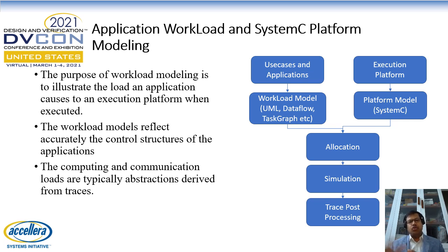And then we have also looked at an open source solution like a gem5 platform, which allows you to simulate different kinds of ISAs. It also has a very flexible memory system configuration, and models written in gem5 can also interoperate with SystemC models nicely. And then finally, we have also looked at the application workload and how these application workloads are mapped onto the platforms on which we want to run the specific workloads, and how after simulating in the platforms we collect the traces and then perform the analysis to see whether we are able to arrive at the right or the optimal architecture for this particular use case or not.